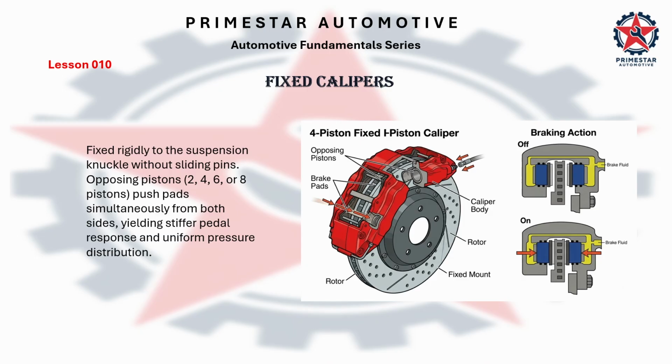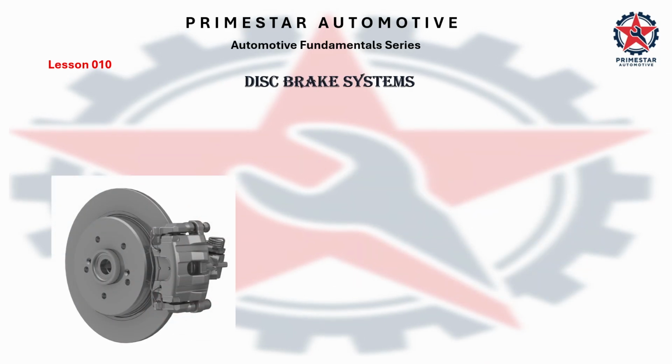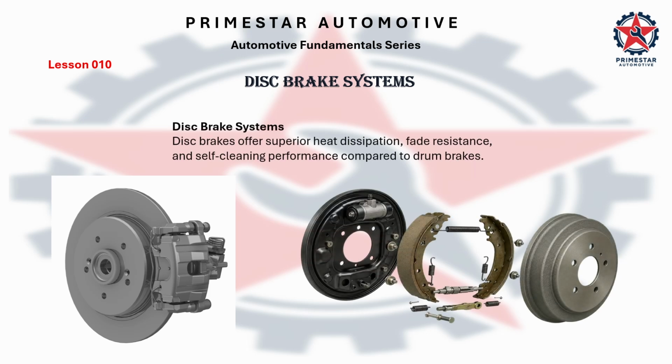Fixed calipers. Fixed rigidly to the suspension knuckle without sliding pins. Opposing pistons, 2, 4, 6, or 8 pistons, push pads simultaneously from both sides, yielding stiffer pedal response and uniform pressure distribution. Disc brake system. These brake systems offer superior heat dissipation, fade resistance, and self-cleaning performance compared to drum brakes.